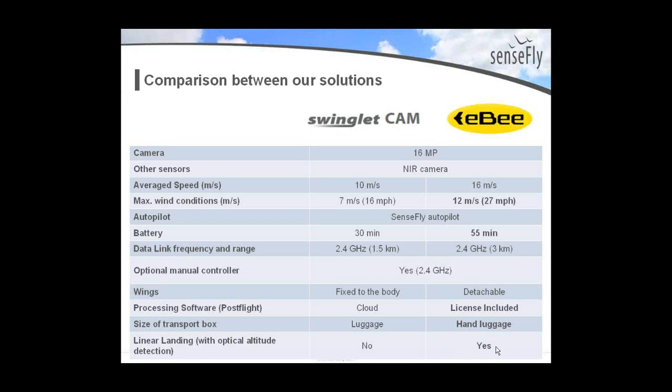And what's nice about the eBee, it'll come in at about a 20-degree landing angle, and so you're able to survey in a very tight area. If you have a lot of obstructions around, you can bring that eBee in at about a 20-degree angle, and you just need about a 40-yard clearance radius around the area you want the eBee to land.